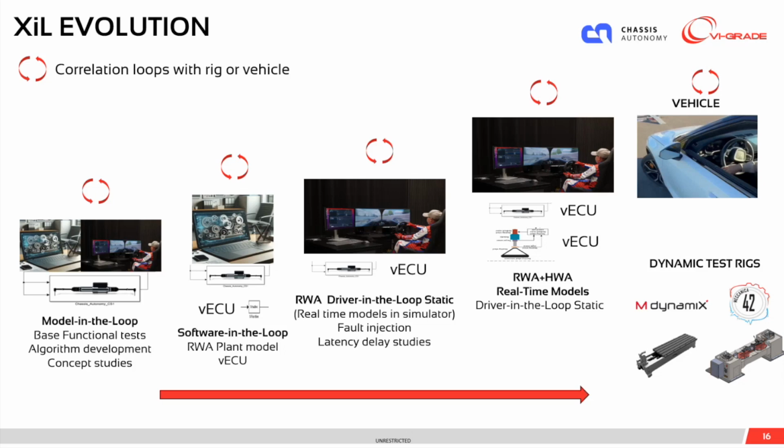The stage after that, the next step would be to bring in your software components. So you have the plant model together with the virtual ECU or an S function. Of course, you need to check everything works offline. Make sure you do that, please, because otherwise you will have some flags not working or something that is very silly that is not working. Then you integrate this VECU, virtual ECU, into your driving simulator to do more detailed evaluations, fault injection, latency delay studies, etc.